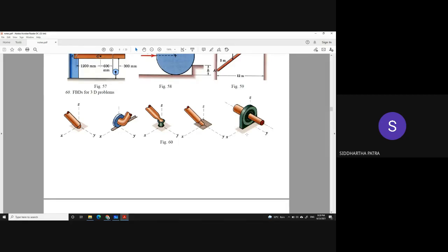But by this representation, what is meant is that the type of load acting on the body would have a tendency to move it in the positive direction. That's why that other end is being made thicker. So in a way, this tells you that the translation in y direction is also prevented. So it would be receiving Ry.